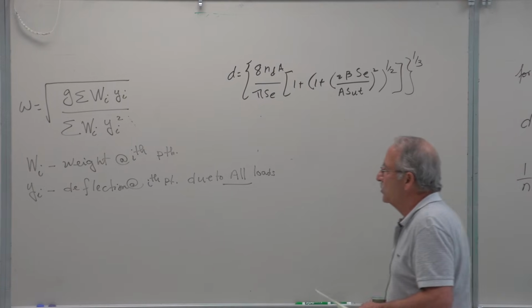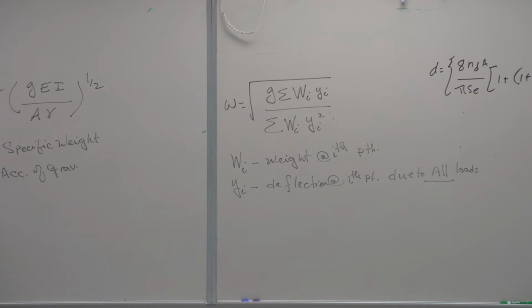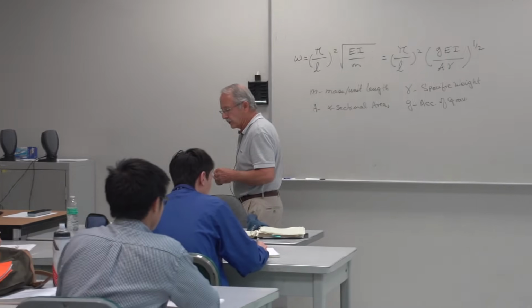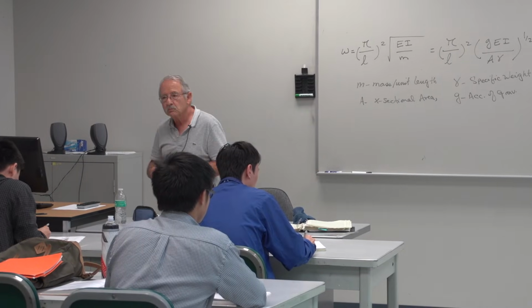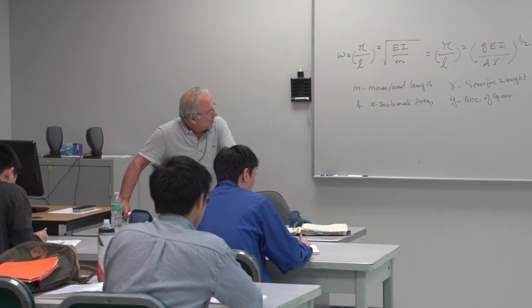You find that frequency and you make sure that it is at least twice that of the externally applied load. Any questions?